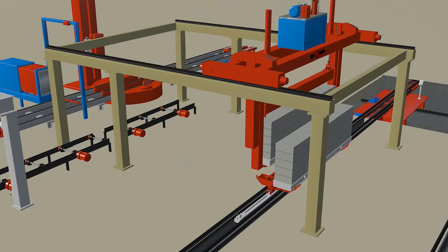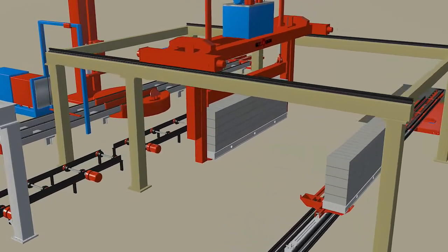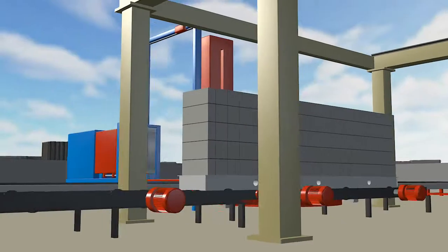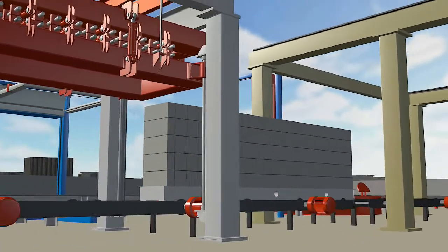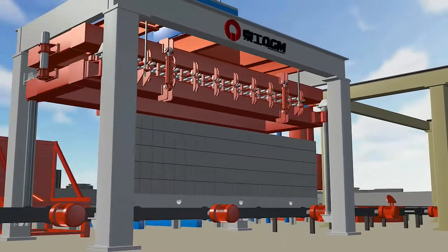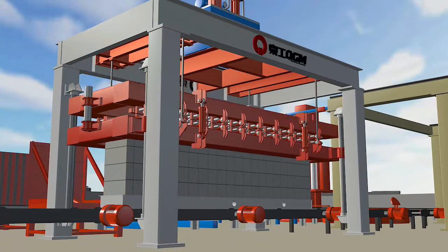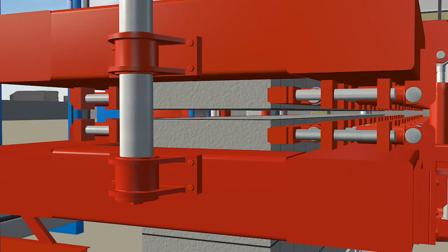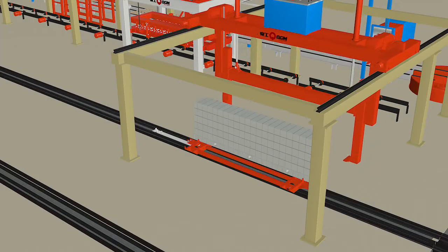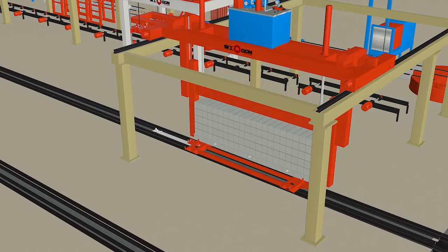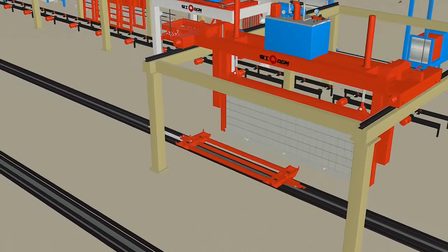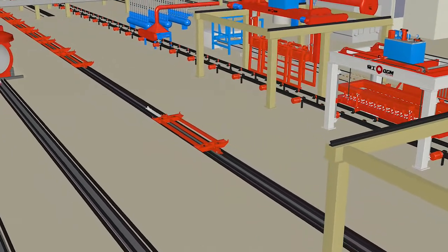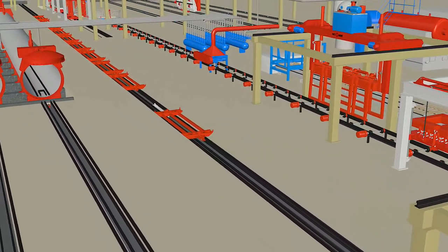The ferry car transports the finished products to the carrying crane, and the carrying crane transports the whole cake together with the side plate to the separating machine for block separating. The autoclaving car goes back to the front of the autoclaves through the orbit, waiting for the new cake.